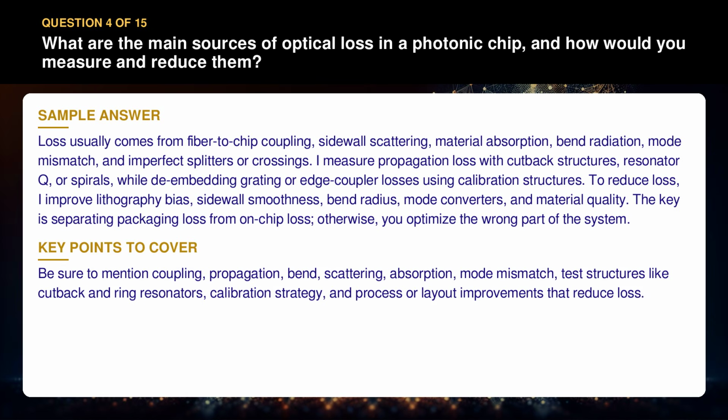Be sure to mention coupling, propagation, bend, scattering, absorption, mode mismatch, test structures like cutback and ring resonators, calibration strategy, and process or layout improvements that reduce loss.